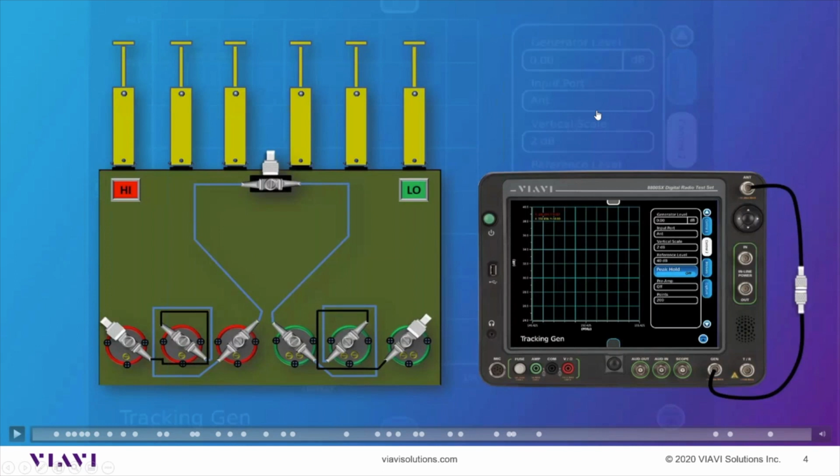Now, before we get started, you would want to take the cables that you are going to do your realignment with and connect them to the antenna port of the service monitor and the generator port of the service monitor, using an adapter and a coupler to couple those together. And then at that point, you'll do a set reference, and then that references out all the loss in those cables, and you can connect it to the duplexer. You're going to see the set reference operation a few times during our presentation here. So I'm going to skip it on the front end here, and we'll just go ahead and get busy here.